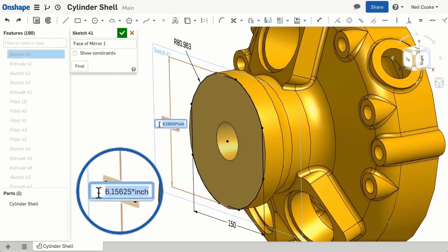If you design in inches, you may want to enter fractions instead of working out their decimal equivalents. I for one don't know what this fraction is, but if it was entered as 6 plus 5/32 of an inch, it becomes much clearer and much easier to measure. Using this notation, you can also mix units. For example, you could define this dimension as 6 inches plus 4 millimeters.